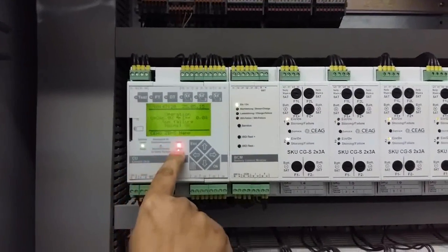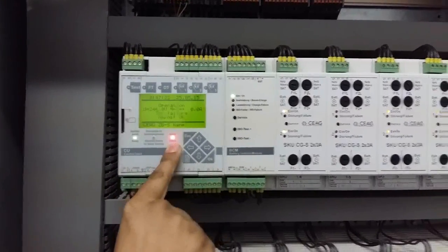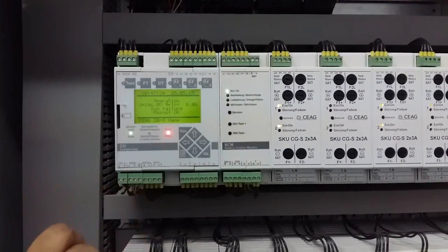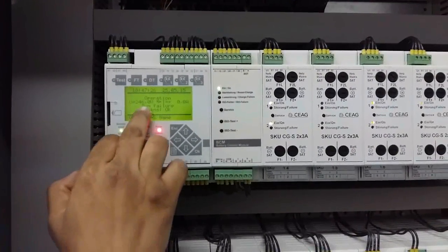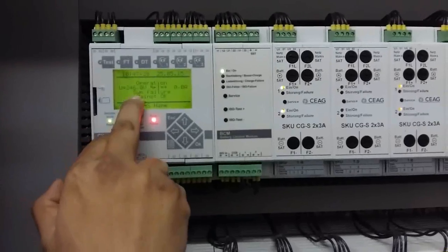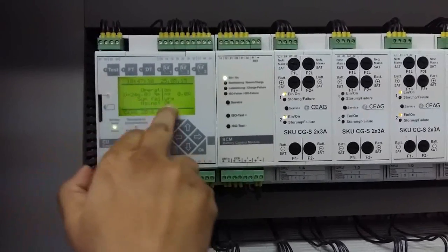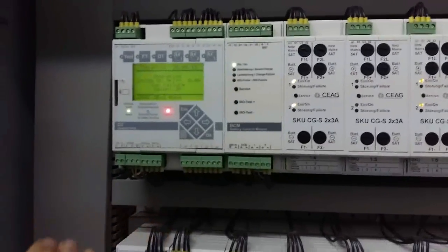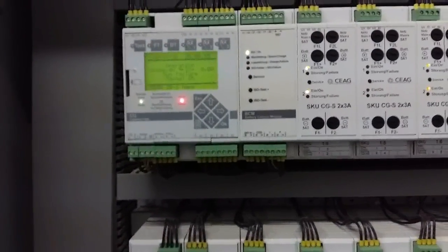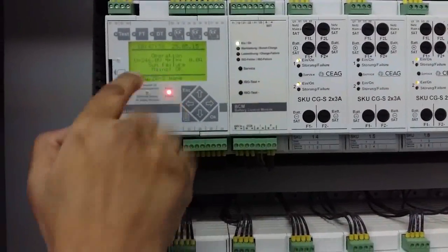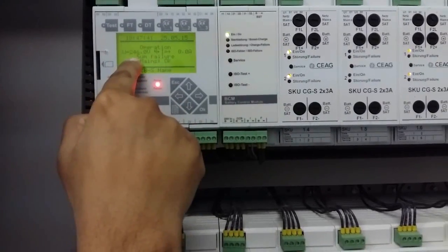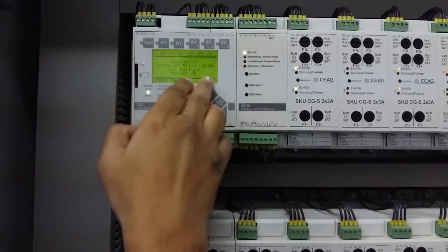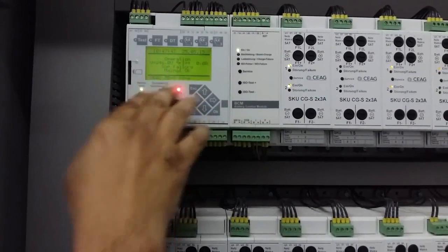So you will find here the red indication. The red indication means there is a fault. What kind of fault? We can check from inside the monitor. You will see this one in the third row, third line. There is some failure. What is some failure? If there is more than one fault, it is called some failure. If it is one fault, definitely it will give the failure like circuit failure or fuse failure or charging failure. But it is having more than one failure, so it is displaying as some failure.